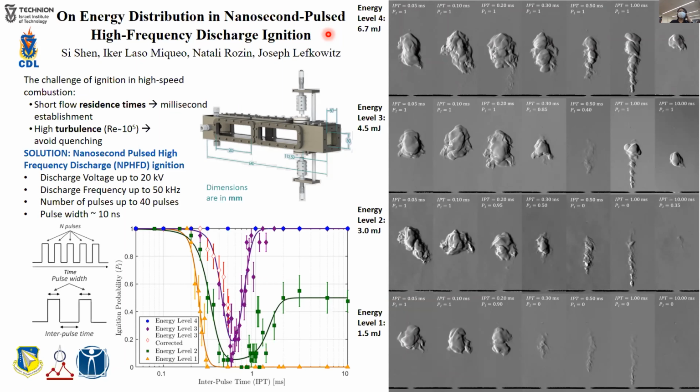My research focused on the application of nanosecond pulsed high frequency plasma discharge as an ignition method for high-speed combustion. Two big challenges we face in high-speed combustion are short flow residence time and high turbulence-induced quenching. We found a promising result using the pulsed plasma discharge.